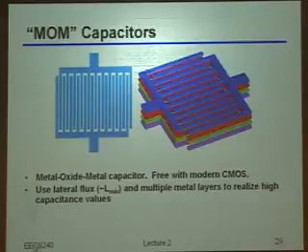The way these are typically built, specifically given that it's these vertical types of designs that are typically most attractive, is essentially you have these fingers that you run, and as you can maybe see here, you stack multiple metal layers on top of each other. And then you have one piece of metal line at either end to make the connection of the complete, let's say, bottom plate versus top plate. And again, you're really utilizing the horizontal fields between the lines to form that capacitor.